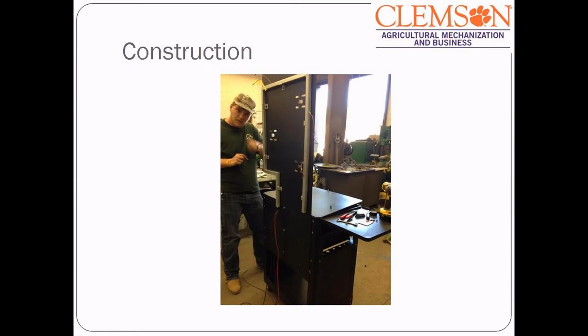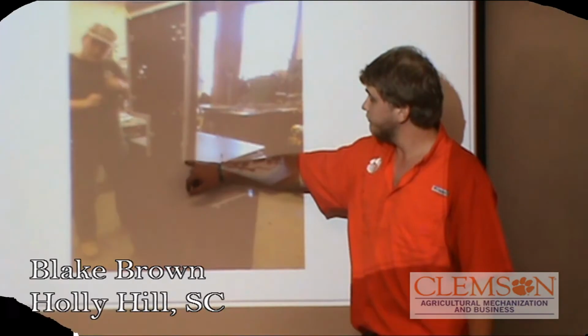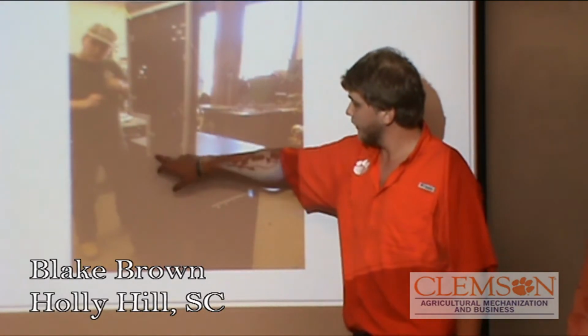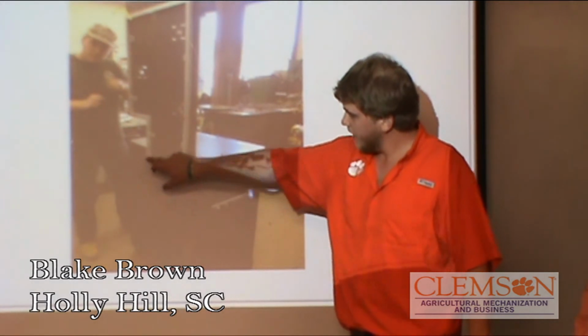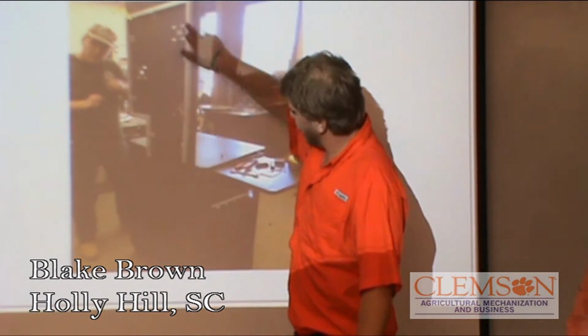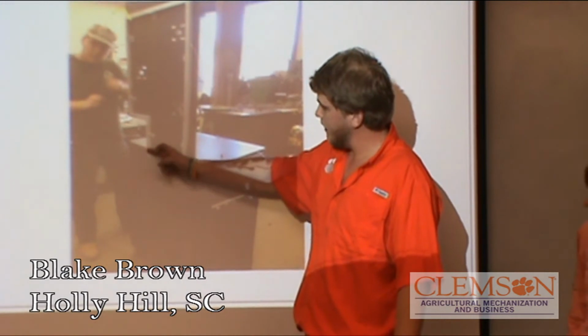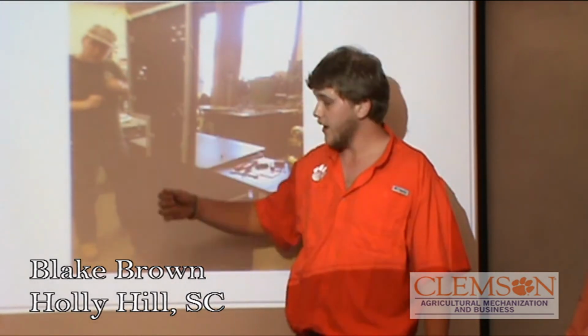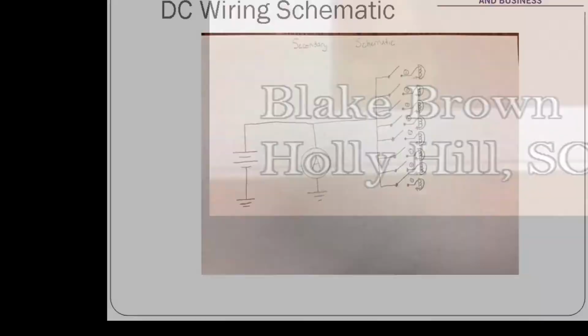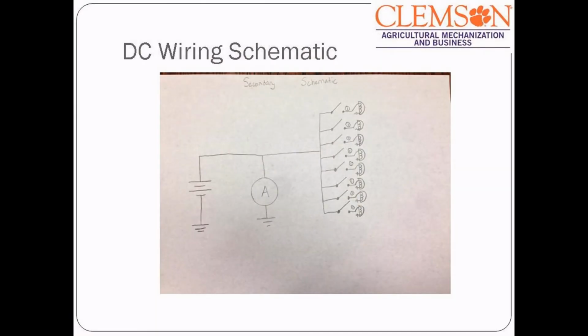This little thing right here is our conduit on the back side. We'll turn it around, you can see it. It is 1-inch square tube, and we fabricated this conduit system, and we have all the wires coming out the back, and they run up in here and all the way around. We took a plasma cutter on the back side and just went all the way around so we could tuck the wires in there.